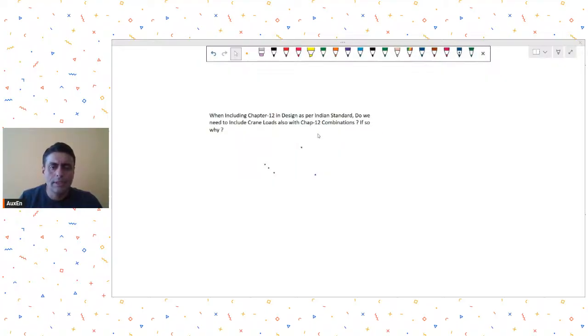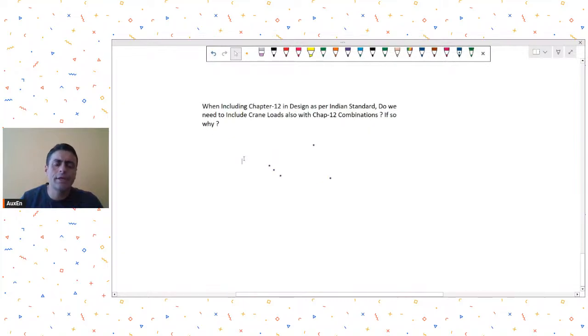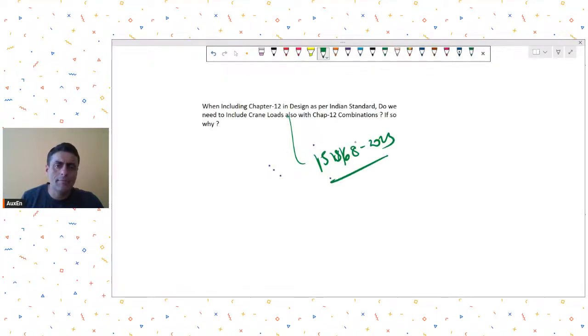First of all, please remember that chapter 12 has now been superseded by IS 18168 2023. Chapter 12 is no longer valid because it has been superseded by a code on ductile design and detailing of steel structures, that is IS 18168 2023.